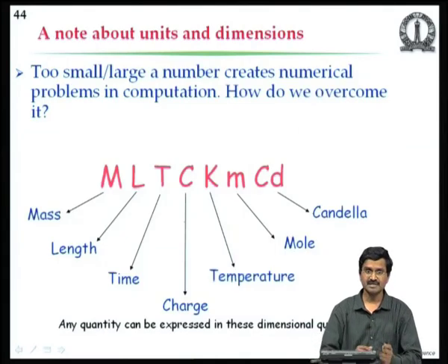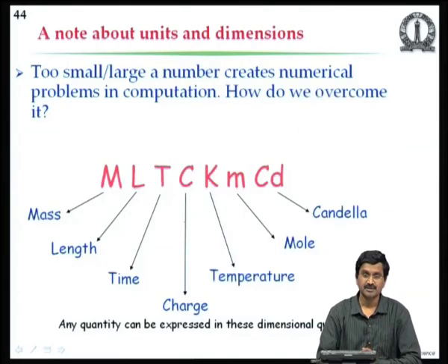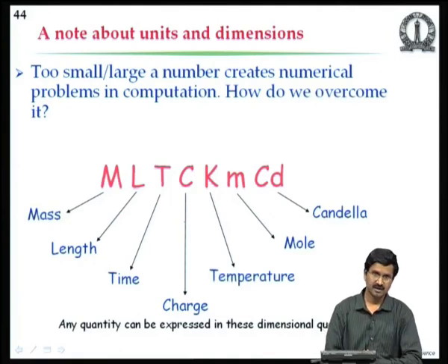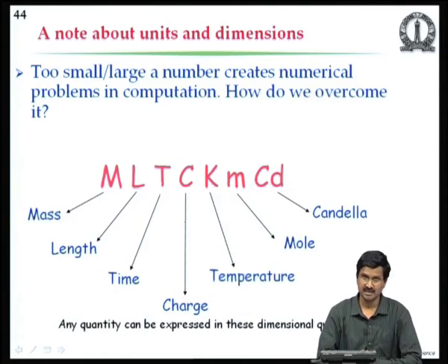And finally, we said that we will discuss the units that we need to use when we do calculations or when we model numerical calculations of the microsystem modeling. If you take a meter as a meter, or a micron as 10 power minus 6 meter, you have to put a very small number into the computer, and that might matter when you square it or cube it.